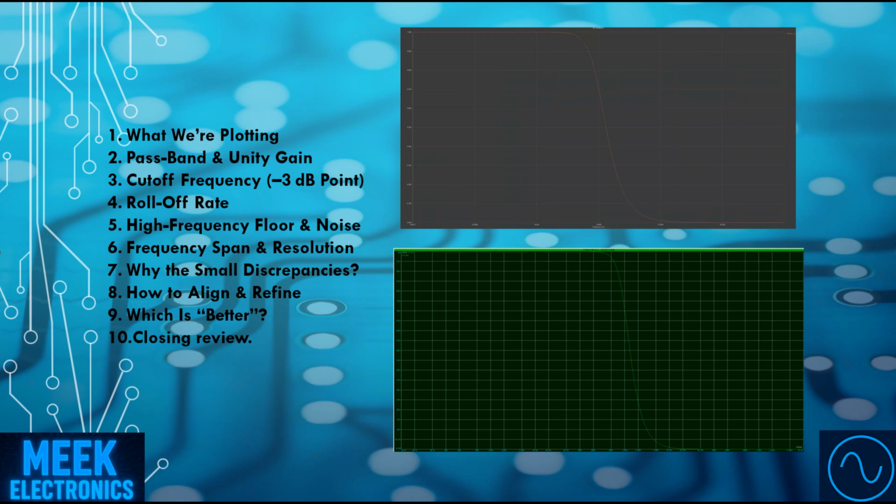8. How to align and refine. If you want bit-perfect agreement, match sweep ranges, e.g. both 10 Hz to 10 MHz. Set the same points per decade, e.g. 100 points per decade. Toggle scale units, plot both in dB or both linear. Adjust solver tolerances: lower the absolute error threshold or noise floor. Use identical component models. Import the same SPICE subcircuit if possible.